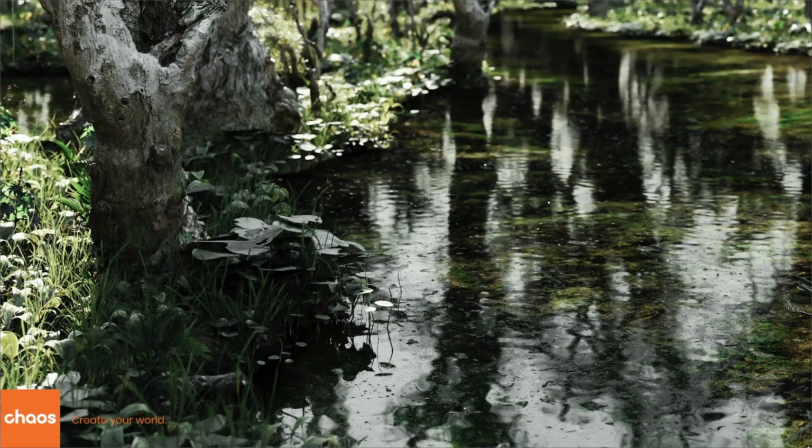Here's another really cool image our coworker George made. Props to you, George. It's a rendered image of a swamp, as you can see. Everything you see scattered here was scattered with the help of Chaos Scatter. For this one, George used the incredibly underrated frequency functionality that's there in this new scattering system. So he was able to control how often a certain 3D asset appears in a given scatter.